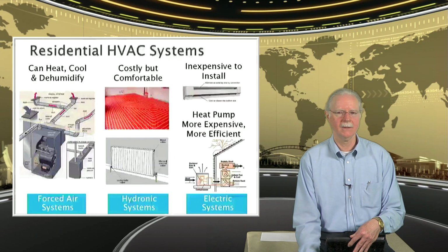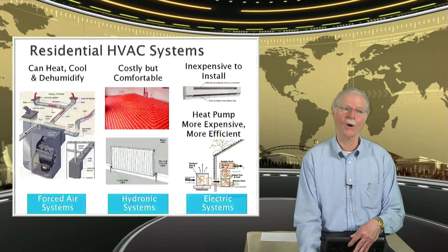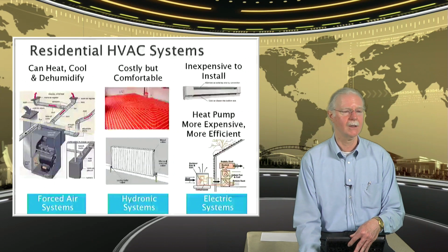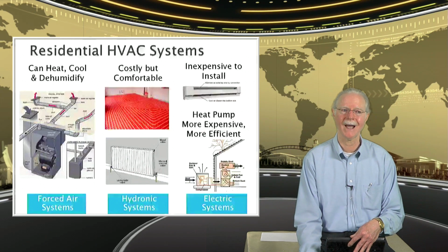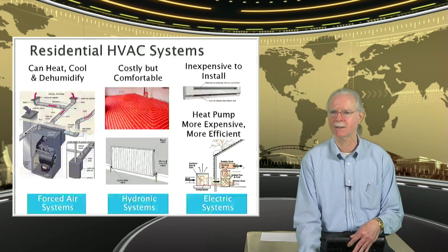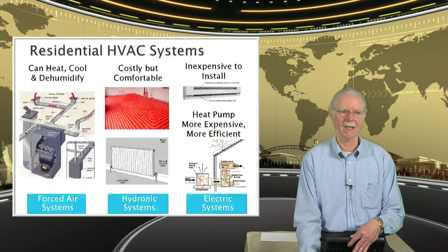We now use air to distribute the warmth or cooling through the residence through an air handler unit. There are parts of the country where air conditioning is called for less frequently, and an efficient system for those locations is often something we would call a hydronic heating system. Basically, it's using water as the heat transfer mechanism. So we use pumps and hot water to move the heat from the source of energy to where the heat is demanded.